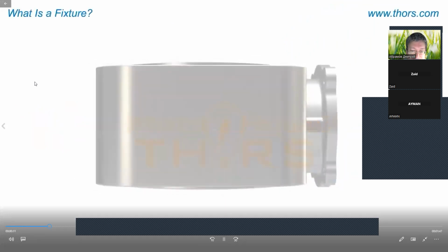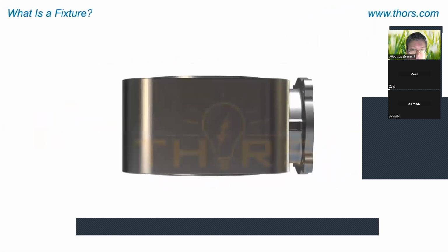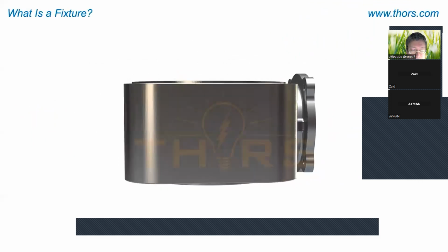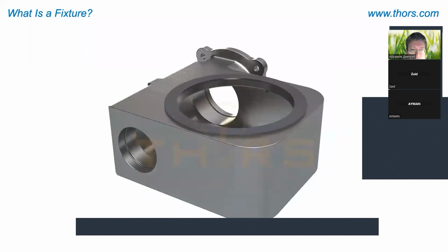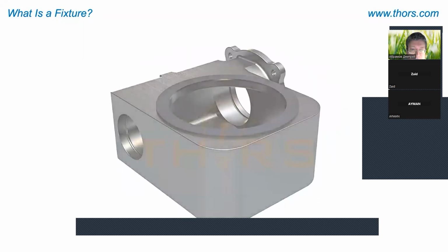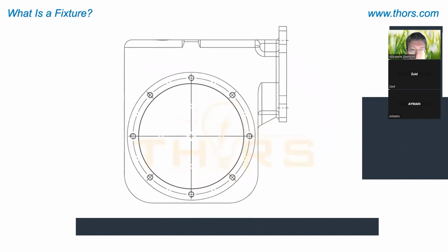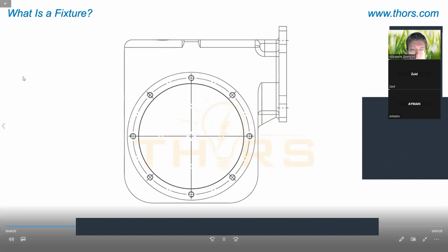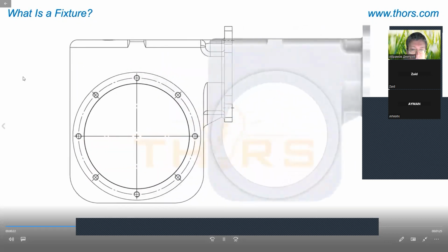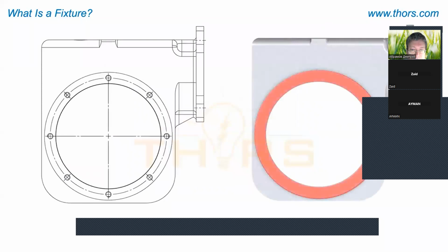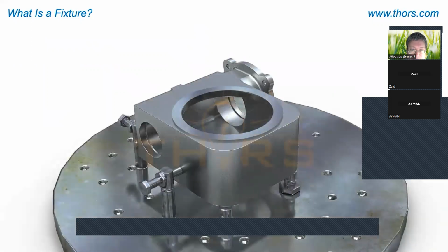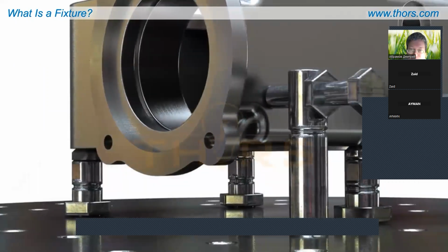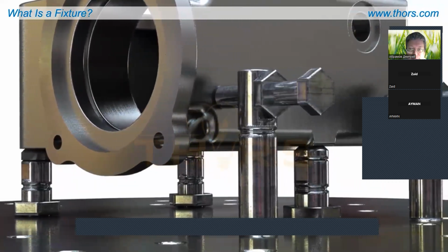What is a fixture? Metal parts created by casting, forging, or other metallurgical processes often require machining operations prior to being ready for service. The casting in this example is a housing for a worm wheel gear. The example here specifies that a boring operation will be performed. The part must be secured so that no shifting or movement occurs during machining. The process of securing the part is known as fixturing or work holding.